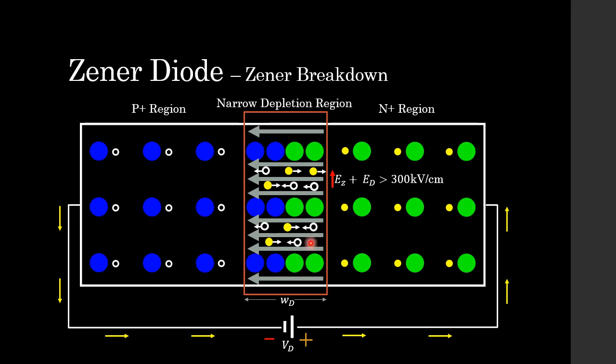reverse bias condition. And now students, if you recall the avalanche effect, this is a very different effect compared to the Zener breakdown effect. The Zener breakdown effect takes place because we have an incredibly strong electric field which actually rips out electrons from the valence band, creating electron hole pairs, and then these free charge carriers move to generate the current. Whereas with the avalanche effect, the electric field would impart kinetic energy to our free electrons, as you would remember.